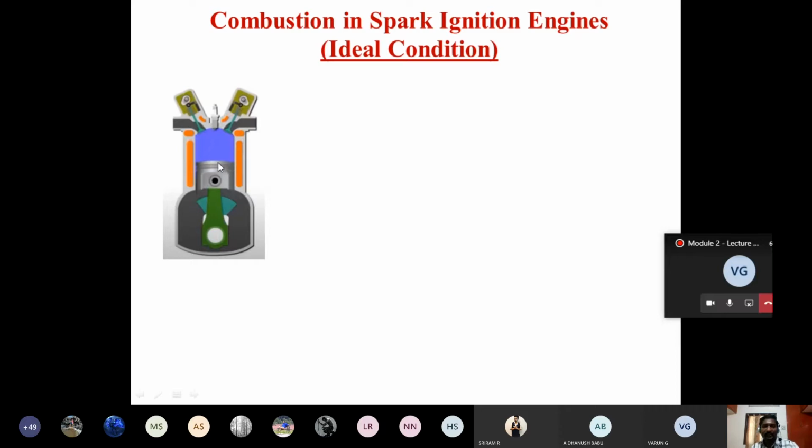So now, where is the piston located now in this diagram? Where is the piston located? Piston is at the BDC. Now compression is going to start. For compression stroke, piston will move from BDC to TDC. Okay. So this is the beginning of compression where the piston is at the BDC, and I am going to draw an engine cylinder pressure versus crank angle turned. Right. This we call it as P theta diagram. P is the engine cylinder pressure, theta is the crank angle turn.